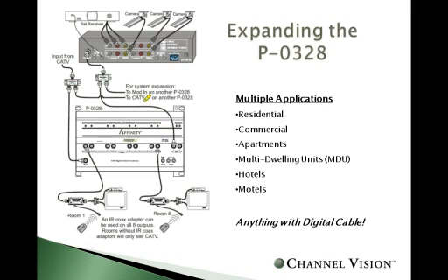The only detail I remind you of is that each room will need a TV kit, an IR receiver, an adapter, and a remote control. So you will have to switch inputs on the television if you're using a cable box, and inputs on the cable combiner switch. So it's a simple one-step solution to be able to view your cameras on the TV.